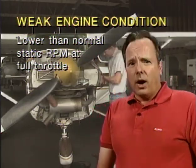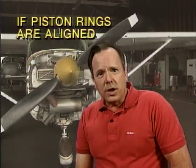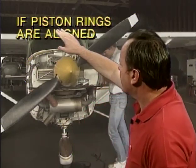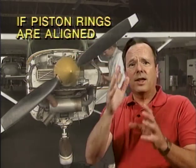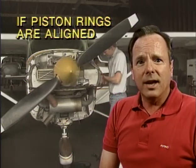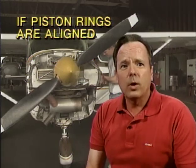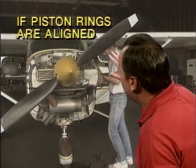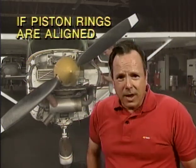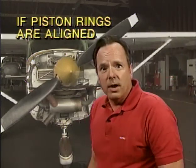Now, if you are having a very, very unlucky day and you do a differential compression check on a cylinder, and all of the piston rings are aligned, with all the gaps in the same place, you're going to have the same indication as if you had worn or defective piston rings, and it would be a false indication. So if all the piston rings are aligned so that the gaps are all lined up, you're having a very bad day. You're going to get a false result of a weak or defective cylinder.